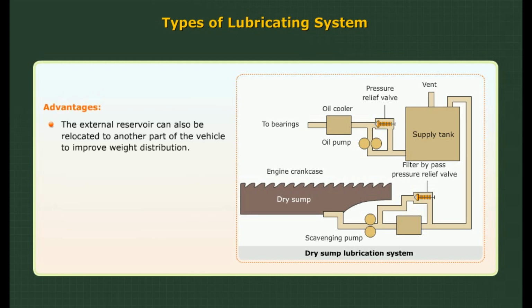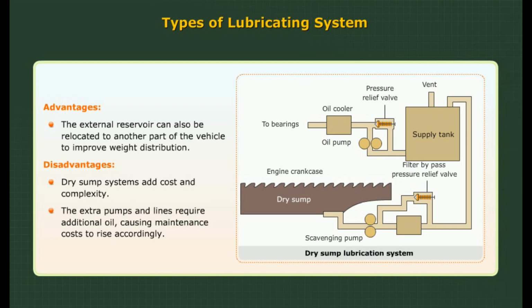Advantages. The external reservoir can also be relocated to another part of the vehicle to improve weight distribution. Disadvantages. Dry sump systems add cost and complexity. The extra pumps and lines require additional oil, causing maintenance costs to rise accordingly.